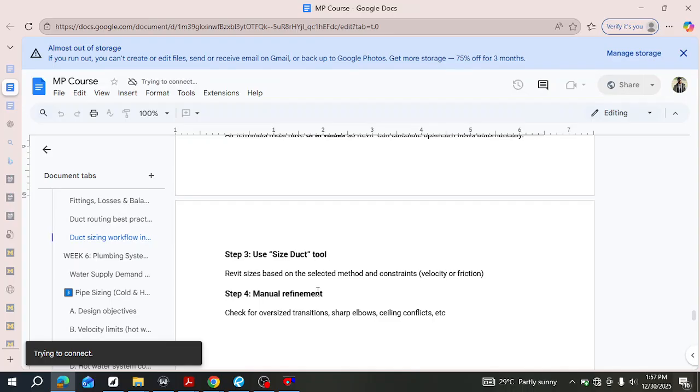So you as a human being, you use your discretion and your intelligence, your years of experience to determine if something is right or wrong, right? There might be some cases where it's going to give you an oversized transition, but you're able to use your eye and check, okay, no, this should not be here, this should be here. So after it has sized your duct, sized your system for you, you make your corrections or refinements, basically, right?